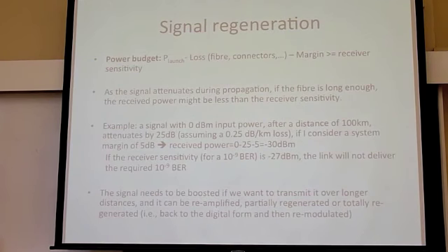Signal generation. So set the power budget. This is the first thing you want to make sure is satisfied, and then you can check the signal to noise ratio. But this has to be satisfied. So you check that. Your input power depends on how much power your laser has. Even if you think of amplifying at the beginning, you can't really, because the more you amplify, the more nonlinear effects you have. We are now neglecting them, but you can only neglect them if you don't put too much power. Otherwise they become relevant, and then you cannot neglect them anymore.